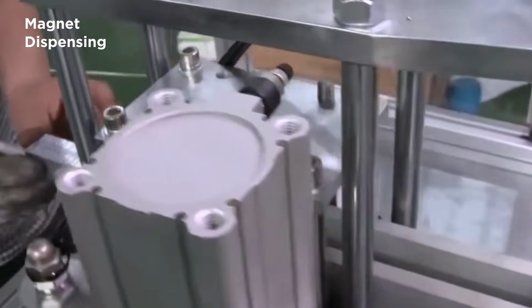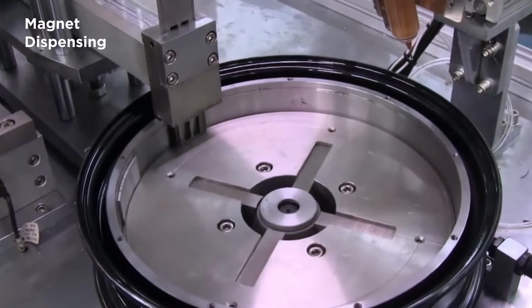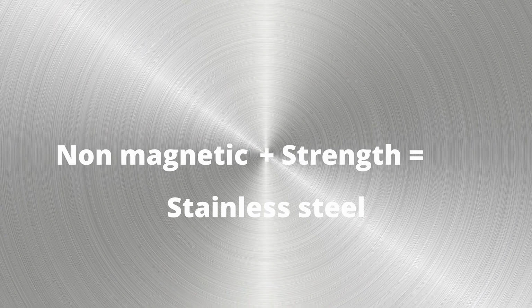Apart from that, stainless steel 304 and 316 both are non-magnetic. So they are also used in applications where non-magnetic material is required. For example, in an EV rotor magnet insertion machine, we must use stainless steel, because mild steel or alloy steel would stick with the magnets during dispensing. Yes, aluminum, brass or other materials can also be used as non-magnetic materials, but their strength is much lower than stainless steel. Therefore, for non-magnetic and strength, stainless steel.